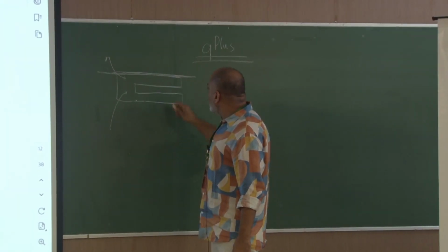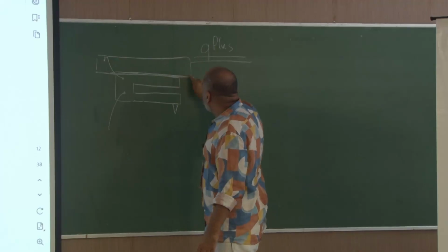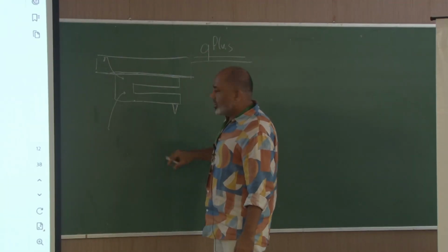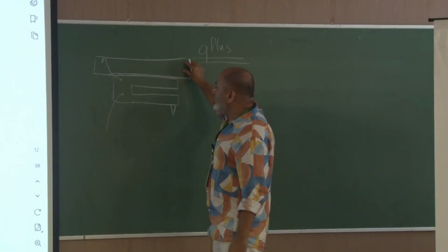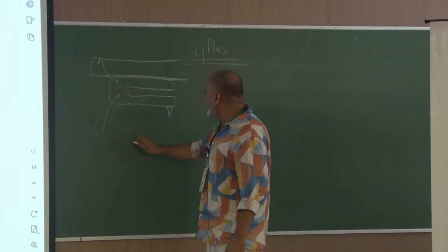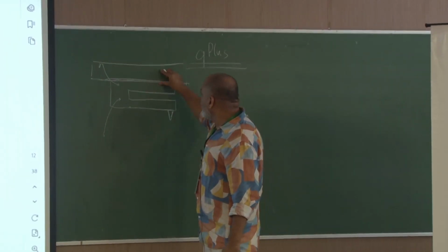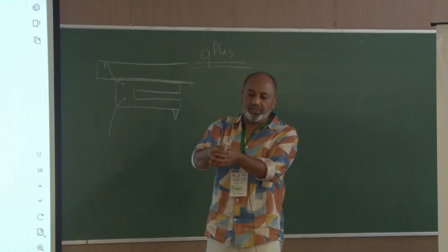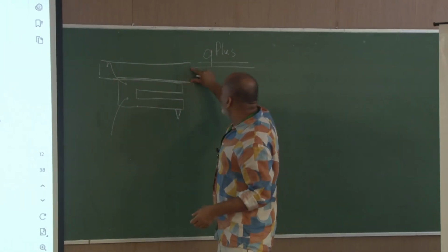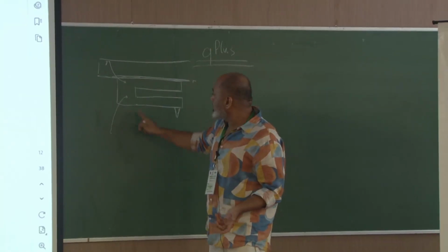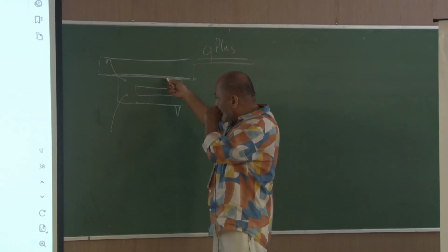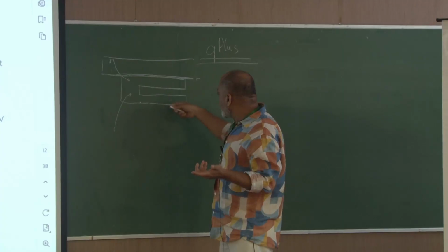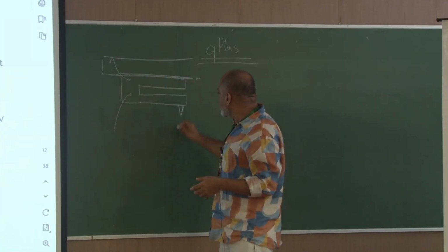So, now you have a tip here, and you hold this on a block, and you shake the block, and this also starts to shake, but if you shake the block on resonance, this will have more bending compared to the other, small oscillations there and big there. And you could also excite it in a self sensing way.